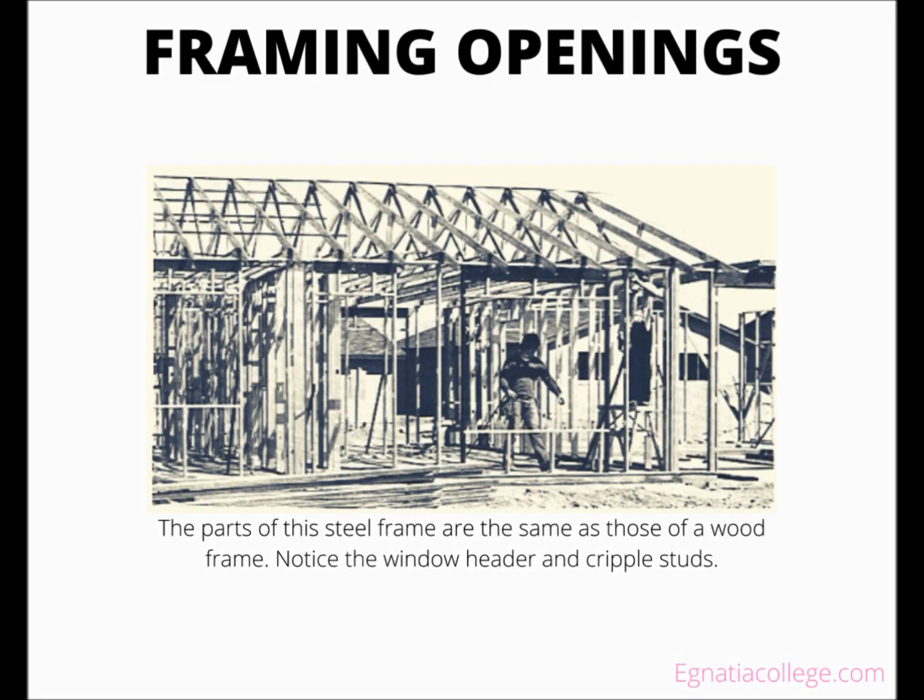The greatest difference is that metal framing is joined with screws instead of nails. Headers over openings in light gauge metal framing are usually very similar to those in wood framing. However, the system designed by the metal framing manufacturer should always be followed.